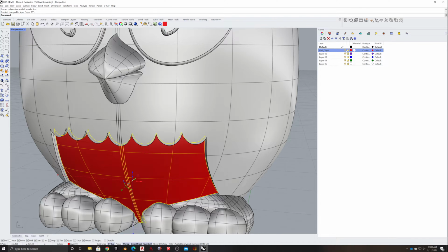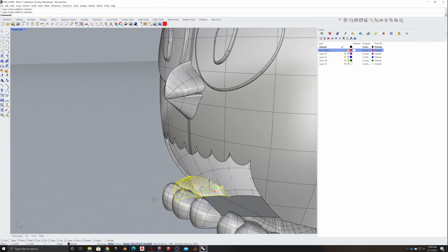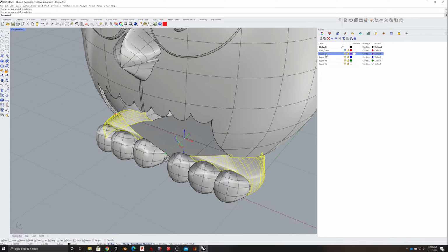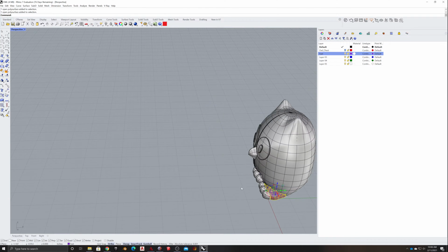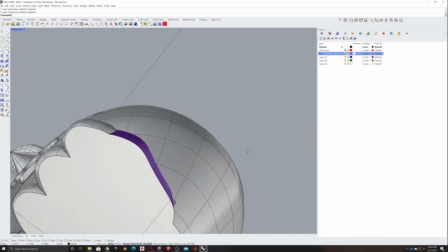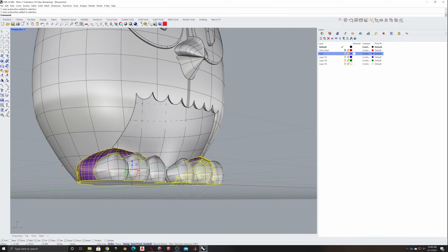And then I'm going to hide it. And if you did it right, it'll hide. And then I'm going to select and continue to do that all the way through. Right click, change object layer, call this feet, join it together. So it's not going to be all one piece, but at least the surfaces are one piece. And make sure I got everything. And you know what? I think I might even put the bottom on that layer too. I can join those together. Change object layer.